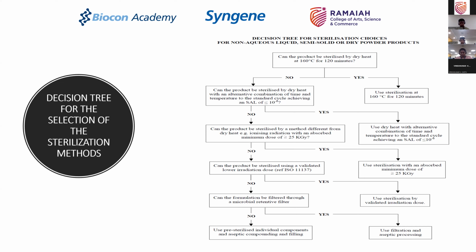So, what is your choice? You come back to the choice that you made earlier. Can I filter the solution through a retentive filter? If the answer is yes, use aseptic filtration and aseptic processing techniques to filter the solution and generate your product. Now you would say, but you said I cannot filter. Yeah, for powders you can't use it, semi-solid you can't use it, but for non-aqueous liquid this is an option.